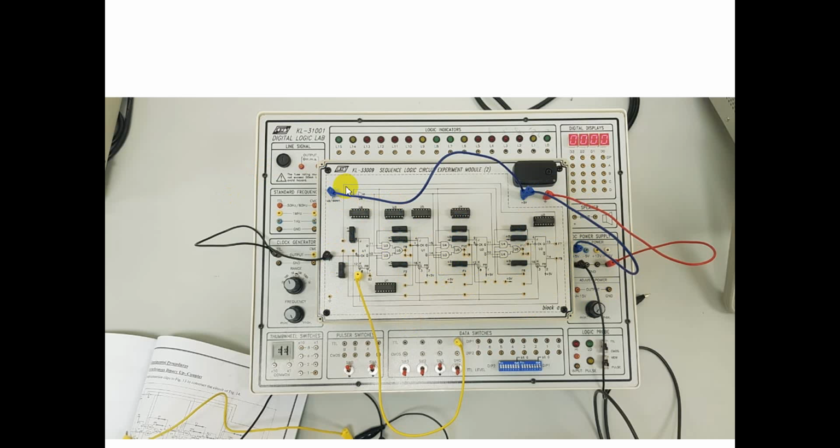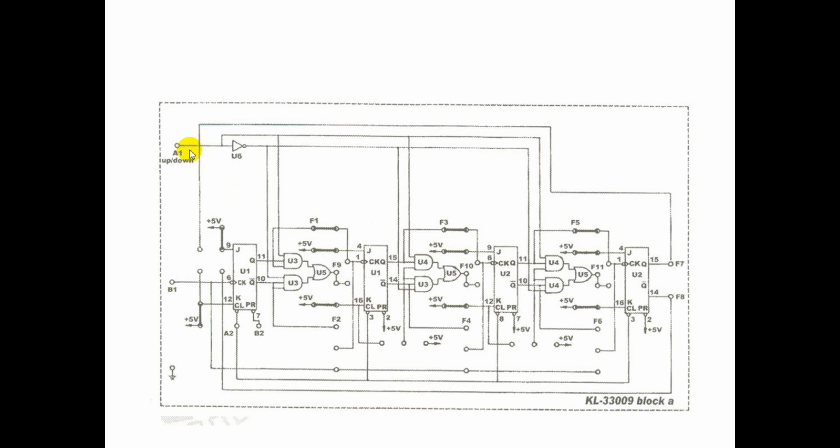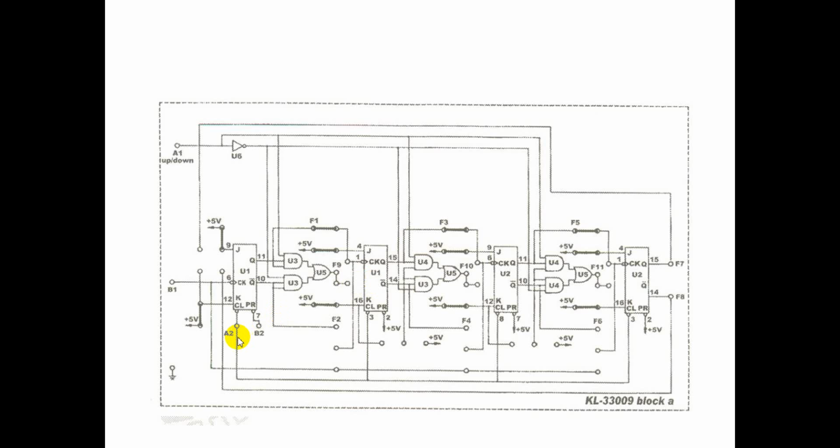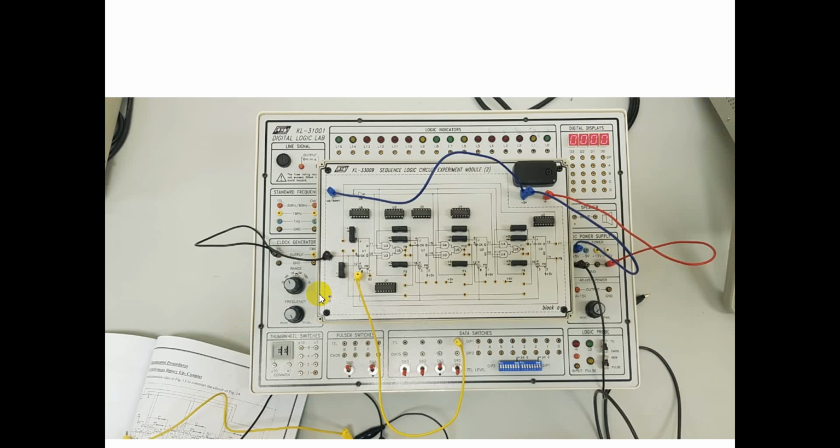According to the manual, it says to connect this input A1 with the +5 here. So I have connected this one with the +5 here. Secondly, this input, I think A2, is connected with the switch, and I have connected it with the switch as per the manual here.